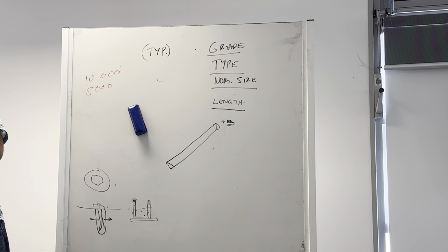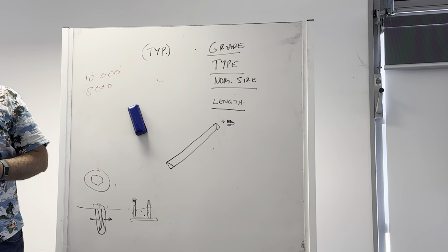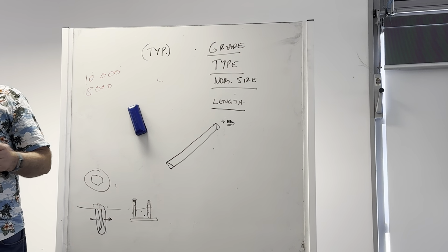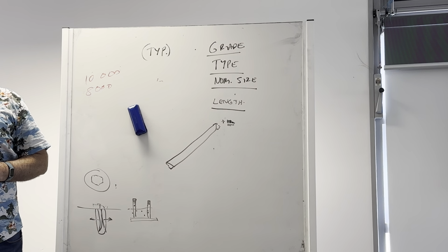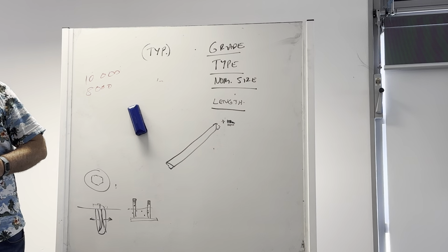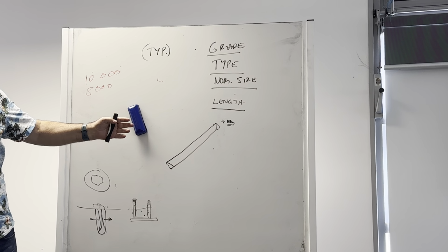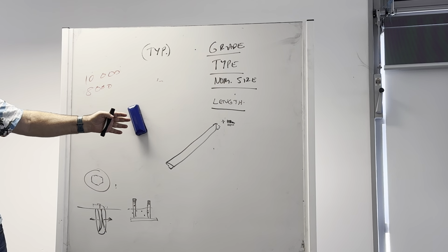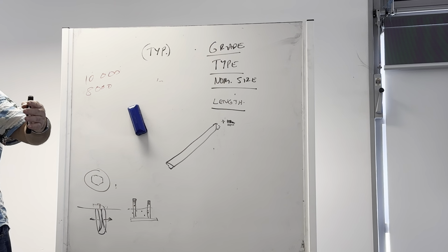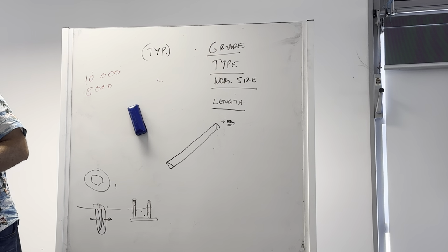So 6.3 metres equals 12 metres of supply. In that case, you've lost about 40%. You're paying 40% more. But you're always better to be a bit over anyway. Nobody's going to criticise you if you take a bit more. Most timber yards will take whole pieces back, so you can take it back to them and get a refund or credit on your docket.